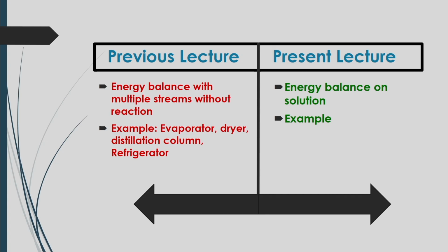Though we have discussed different aspects of mixers and also how to calculate the enthalpy changes of mixers in a particular process, and based on the mixer specific heat capacity and temperature change, how that energy can be calculated based on internal energy change and also kinetic energy change inside the system.